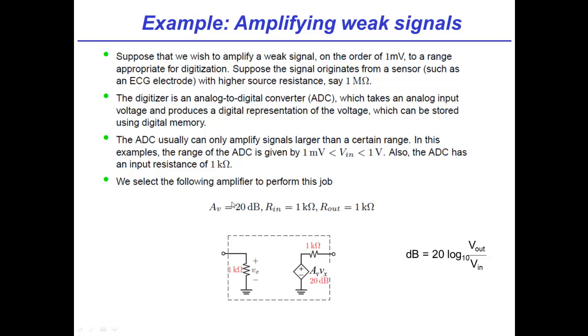Now, some of you out there might say, wait a minute, we've never seen dB. Why are these guys introducing this? But here's a good point to introduce what a decibel is. We're going to cover this in a lot more detail later on in the course, so you're probably bored to death of it. But for the moment, a decibel is really just 20 times the log base 10, not natural log, of the ratio between the output and the input voltage, defined however we want V out and V in to be.